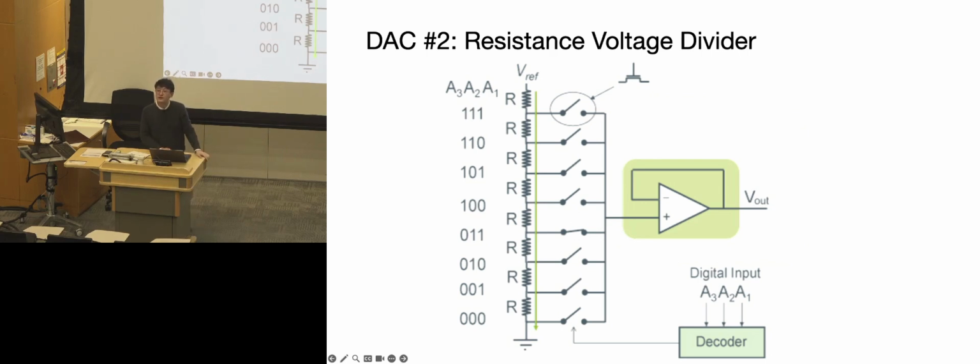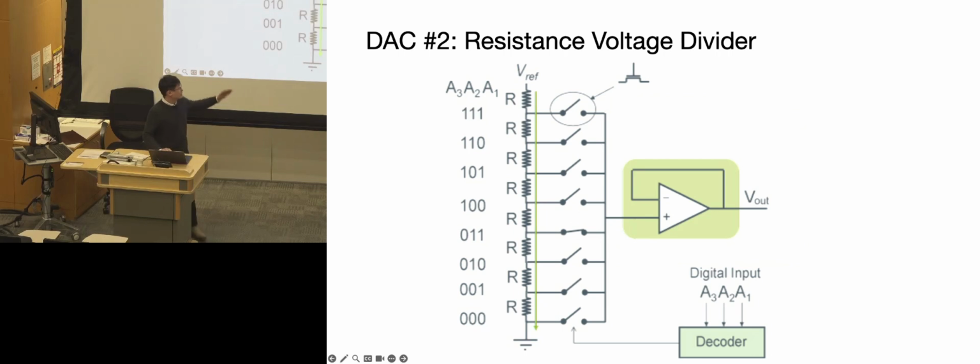Any questions? Yeah. Can you explain what the op amp is doing again? The op amp, you can think of it like a holding stage, so that it makes the V out of the system independent of the load put on the outside circuit. Any other questions regarding this? I will also show you a circuit design on how exactly it works.